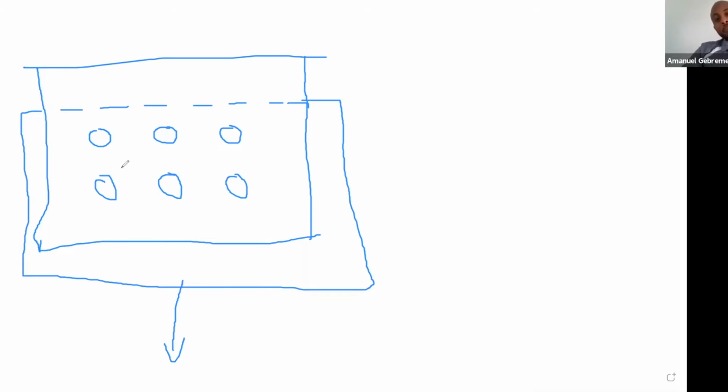So everyone is familiar with designing, let's say, this plate here. Let's look at this plate, the inside plate, the smaller guy, for shear along, let's say, this zone, which is in yielding. You'd essentially just check that member for tension in yielding.